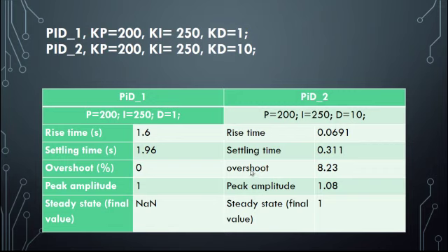After that, the PID controller has optimum control dynamics, including the highest stability, short response time, zero steady state error and no oscillation. The reason to use the derivative gain KD in addition to the PI controller is its ability to predict the error and decrease overshoot.